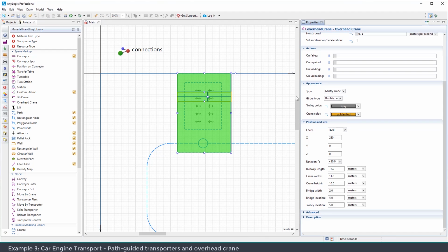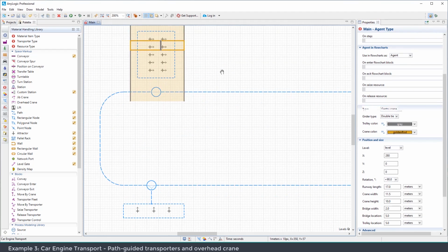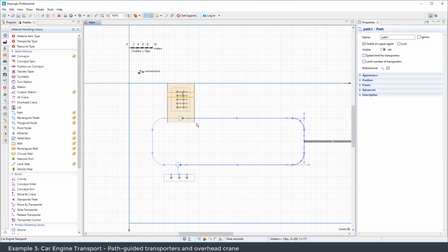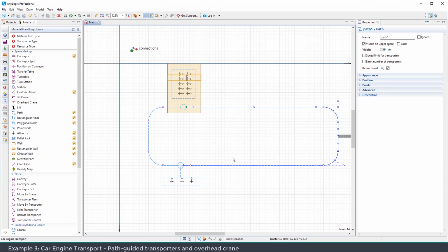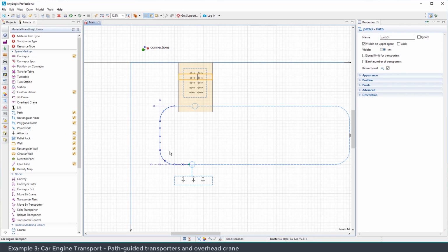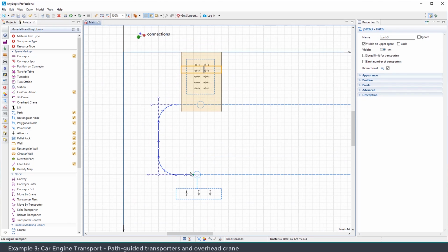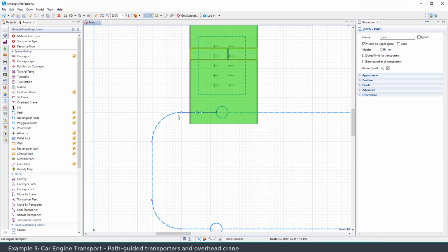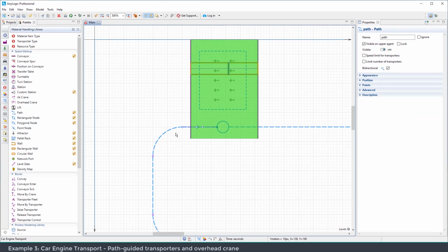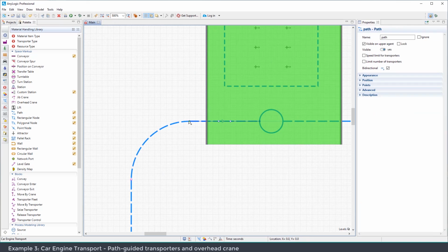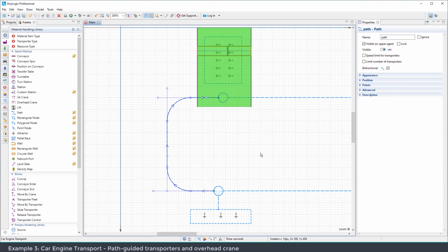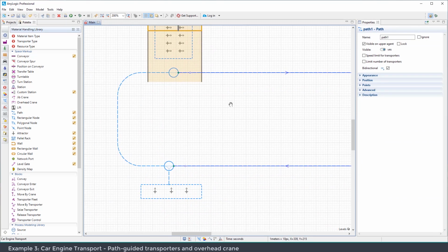One important caveat is that adding point nodes separates the path into several sections, and we have to make sure they are all correctly connected after the breakup. As you can see here, we have 2 sections that are not connected properly to create a continuous path. Therefore, I need to move these sections and reconnect them. Now we have 2 continuous sections that are also connected with the 2 nodes.